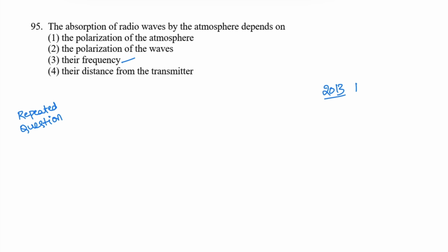So ducting propagation occurs only when the height of the antenna is less than the height of the duct. Look at this image here. The blue line indicates the height of the duct and the green line indicates the height of the transmitting antenna. In this case, the height of the transmitting antenna is much smaller compared to the duct height. The red color indicates the trapped electromagnetic wave propagating inside the duct. So this diagram shows this.